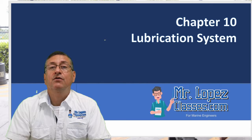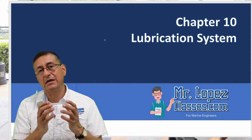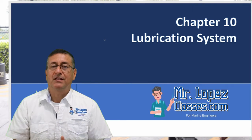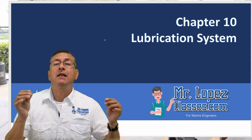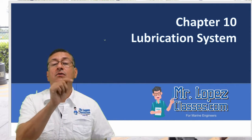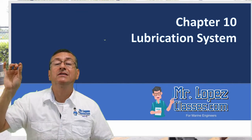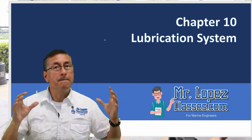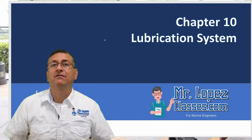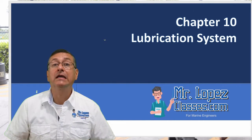In that video clip, I am going to explain the procedure to analyze the report of the oil sample when you send the oil sample to the laboratory, and we are going to analyze all the possibilities. We are going to check metal by metal found in the report, and what happens if I have an excessive amount of that metal. Where is the problem located, the possibilities, and what is the solution for each case. It's a big table that we are going to create in the classroom, and I hope that you enjoy that video clip. This is one of the bonus video clips that we are going to have in this course.